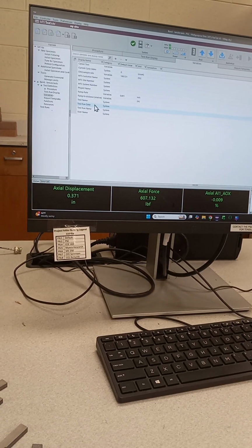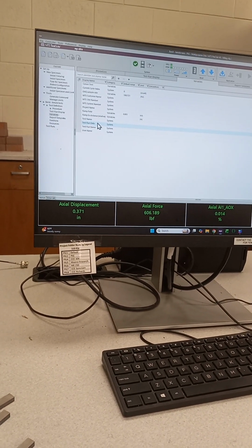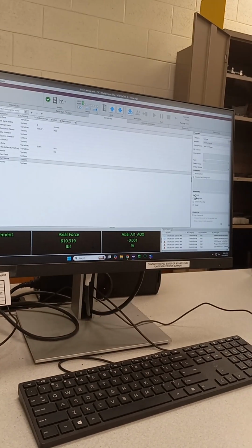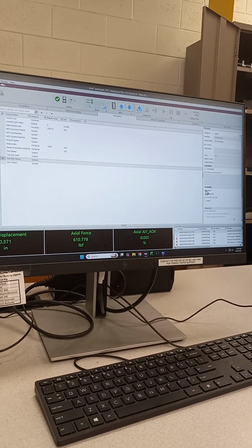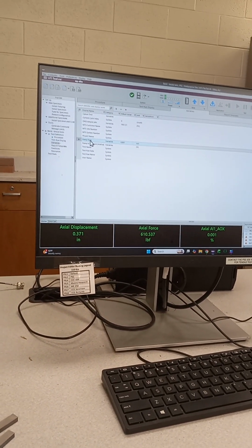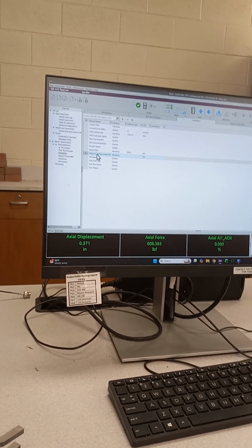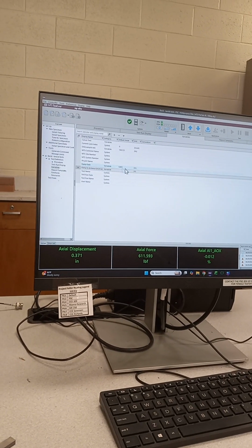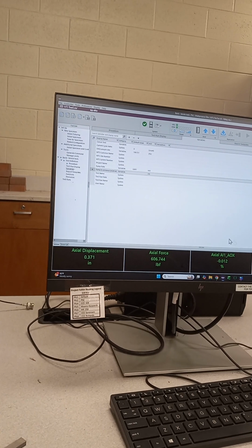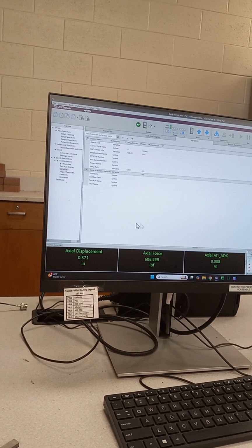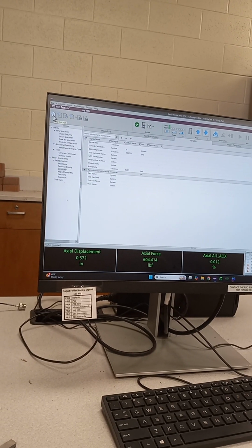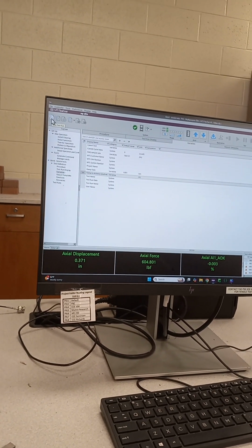If I go to variables here, I know one of them is going to be test run name, and it should have a check mark there on pretest for it to pop up at the beginning of the test. So that one, and the ramp rate should have it, and the ramp to distance should have it. So all the things we want to configure at the beginning. If there's anything that you don't want, you can just uncheck it. And now I'm just going to pretend like I'm running a test, and I'm going to cancel it. I just want to see the window pop up.